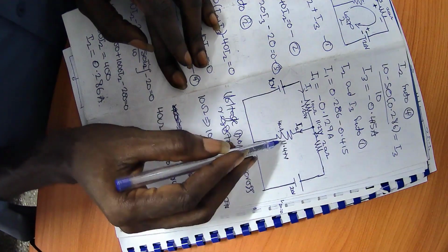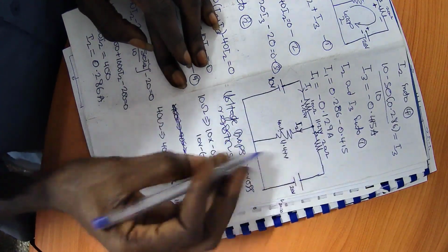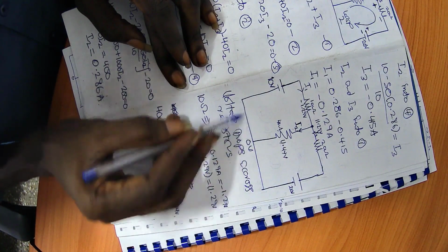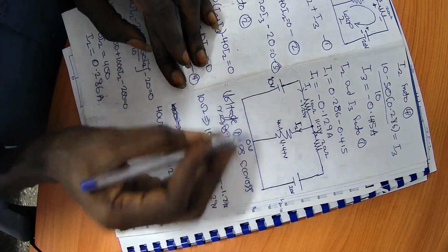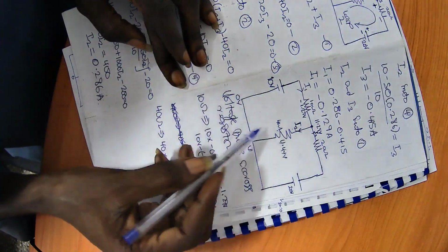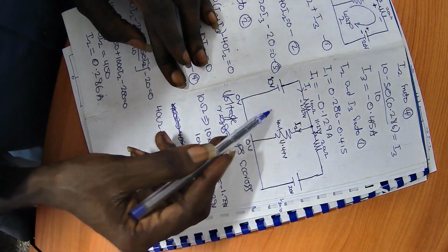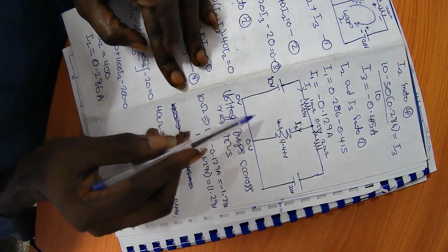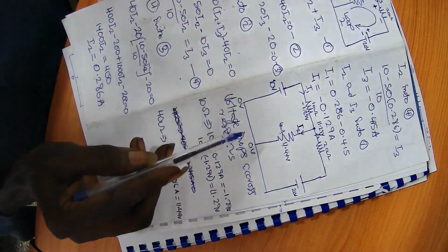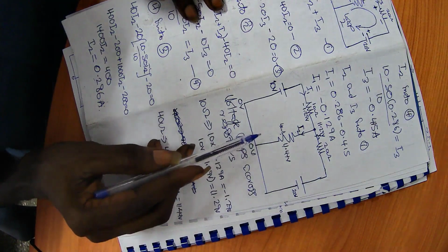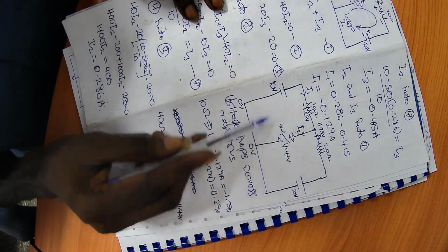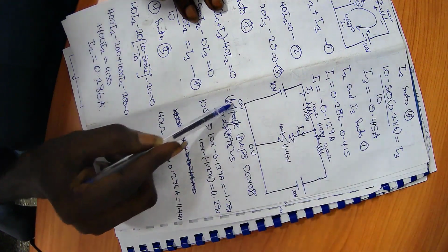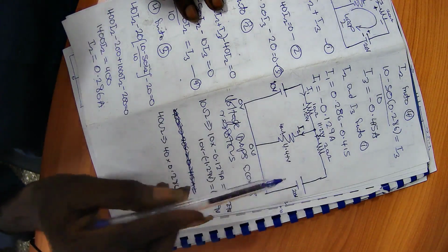So that means that if you subtract this 11 from this 11, here will become 0 volts. If here is 0 volts, there is no load here, so there is no voltage drop here. So that means that here also becomes 0 volts. So the sum total of the voltage in this loop is 0 volts, which makes our work correct according to Kirchhoff's closed loop rule, which says that the sum of the voltage in the loop must be 0. So here we got the sum of our voltage to be 0. Okay, all right. Now let's come to this particular loop also.